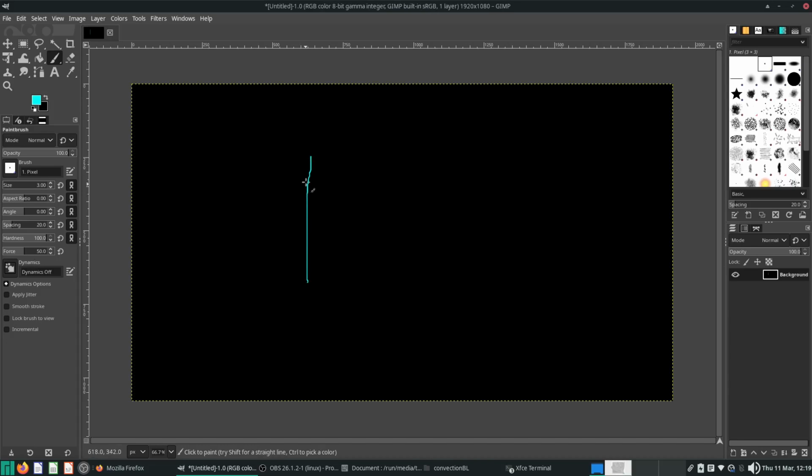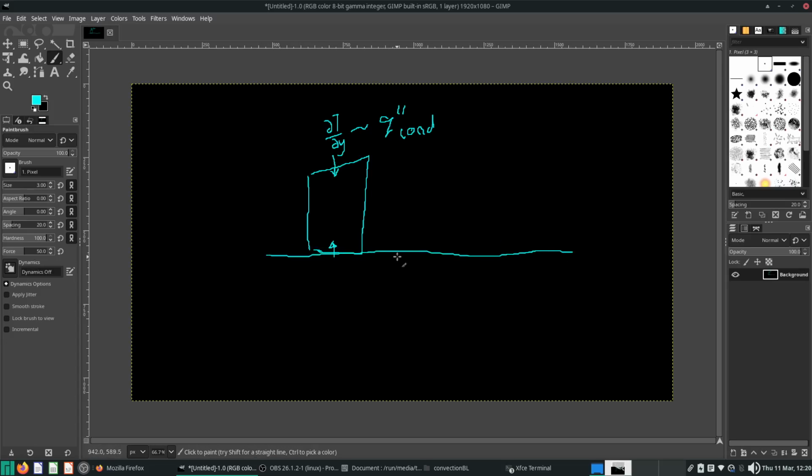So again, we have our thermal boundary layer. This is partial T partial y, which represents the conduction heat flux, just to be very clear. The conduction heat flux at the edge of this boundary layer is very much 0. We neglected conduction for everything except the fluid in direct contact with the surface. This is the surface.